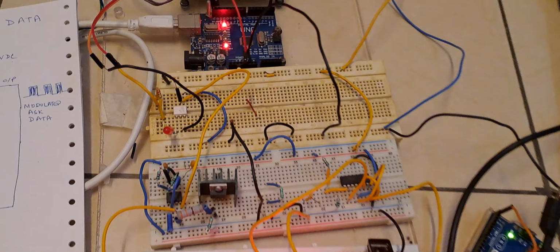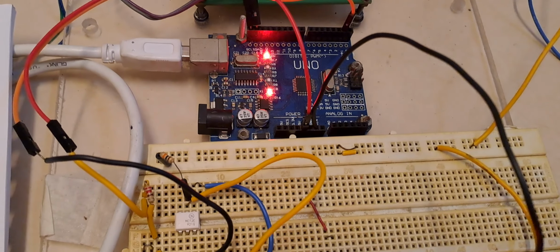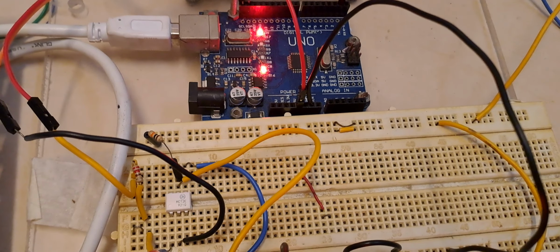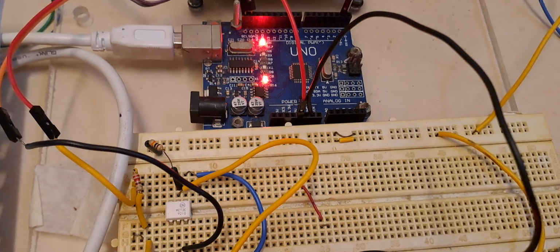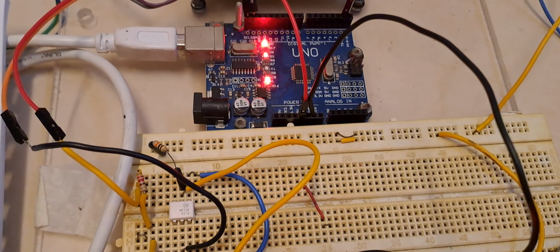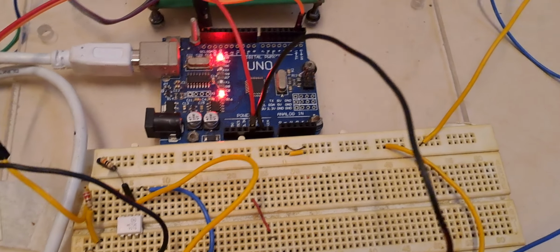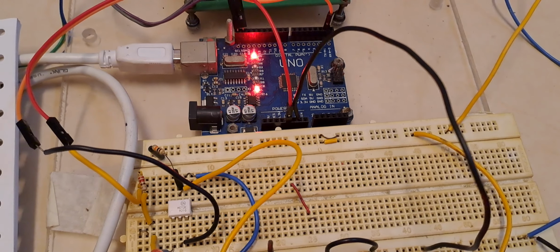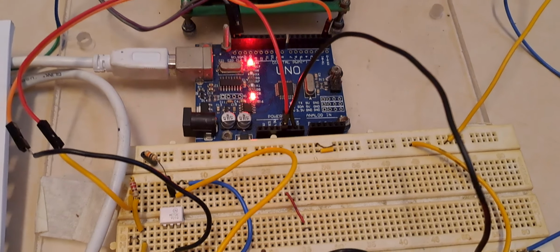Hello everyone. In this video I am going to demonstrate data transfer between two Arduino boards using ASK modulation scheme. I am going to transfer 9600 baud data between the two Arduino boards. I am going to use 48 kHz carrier signal to modulate the data. So the data between the Arduino boards will be modulated using a 48 kHz carrier signal, and we will be